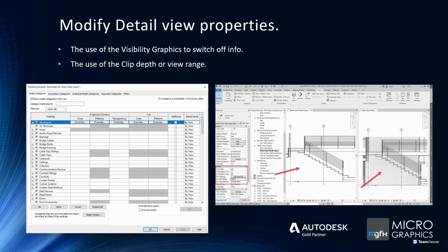All right. So just looking at the view properties that you can turn on and off as you progress from the design stage to the documentation stage. There are different ways to do this, and I did mention a hybrid modeling detailing concept, and that's where you use some of the 3D model that you have, your building, your walls, your staircase or whatever, and you use that in your detail. I'll show you in the demo a little bit later what I mean, and then perhaps an alternative to that.